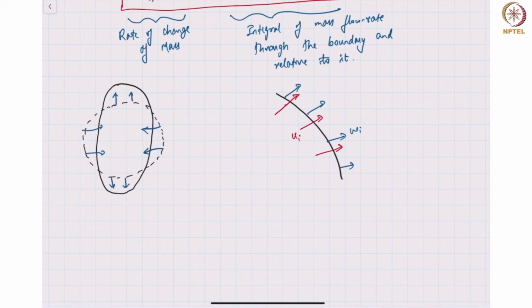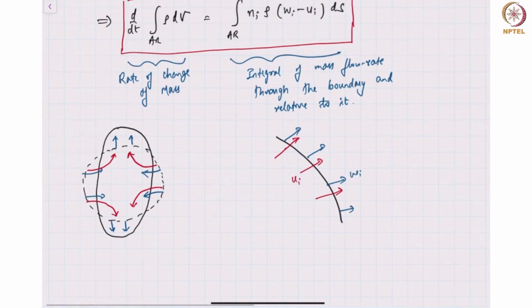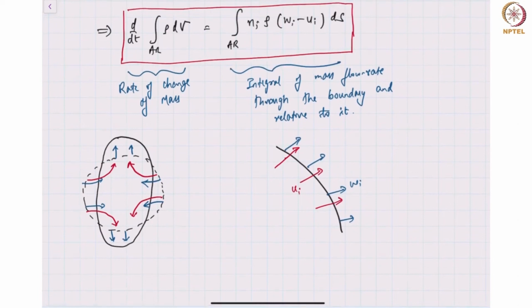As shown with the blue vectors. And because the boundary has evolved, mass simultaneously has also traveled from the bulges on the outside to the bulges on the upper half. So the fluid has to travel so that whatever mass is contained inside the boundary remains inside the boundary. In this particular case, the total rate of change of mass, the left hand side, is 0, and on the right hand side, ui minus wi at the boundary is also 0. Therefore, the equation is identically satisfied.